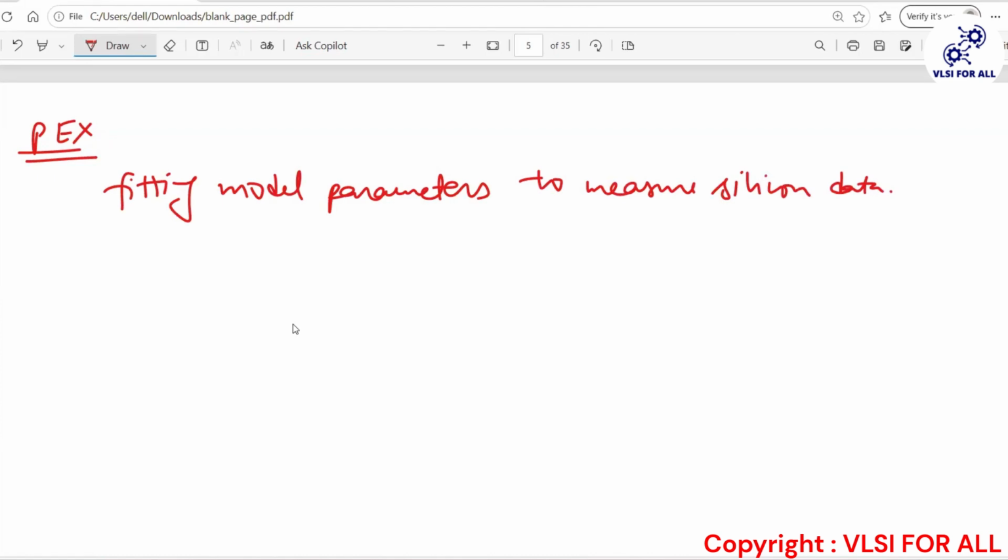Correct. Now, how does our extraction flow start? It starts from wafer fabrication. After wafer fabrication, we have the electrical measurements: the DC values, the capacitances, and the AC measurements like noise, frequency and temperature. After the electrical measurements, we go for data pre-processing, and we optimize everything. Then we use the Spice model parameter extraction and model validation to create the correct model generations, right?